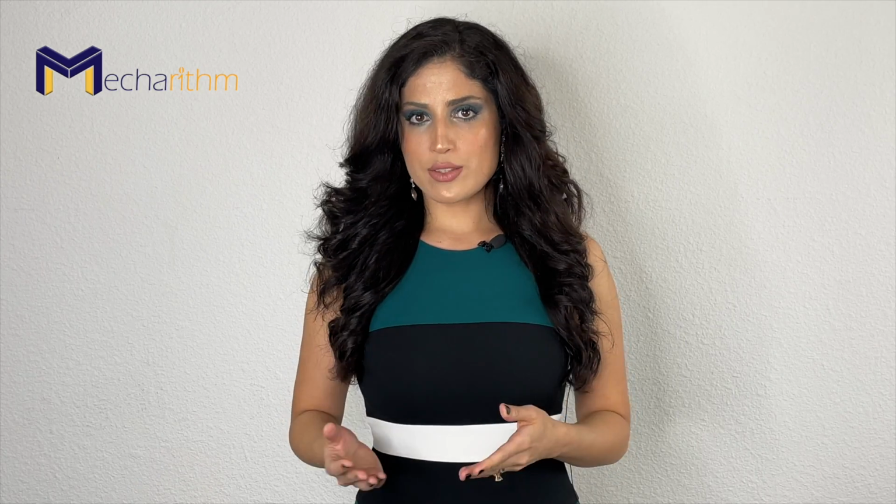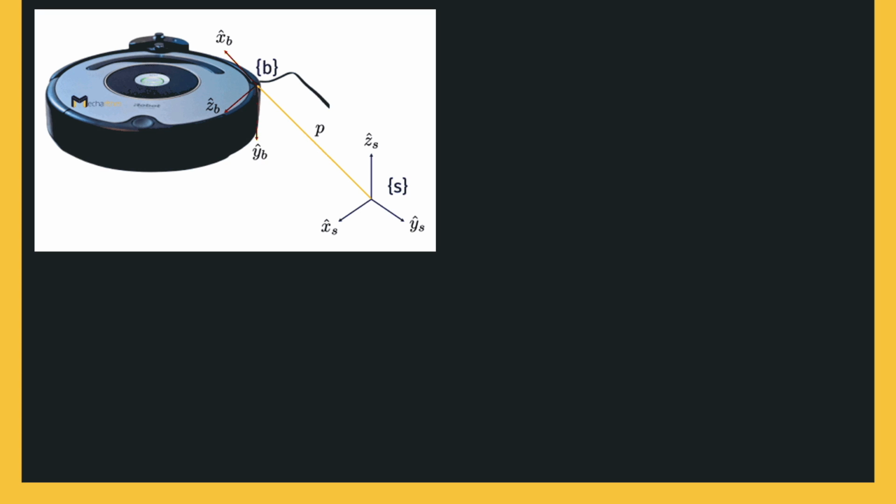Now we want to express the angular velocity with respect to coordinate frames. We can choose a coordinate frame for angular velocity, and our natural choices are the space frame, or S, and the body frame, or B. If the rotation axis is defined in the S frame, then the angular velocity expressed in the S frame can be written as this equation, in which omega hat S is the unit axis of rotation and theta dot is the rate of rotation about this axis. The axis of rotation is expressed in the S frame.